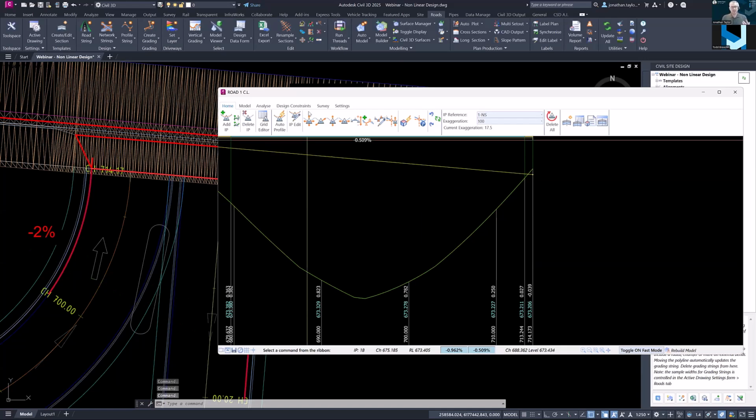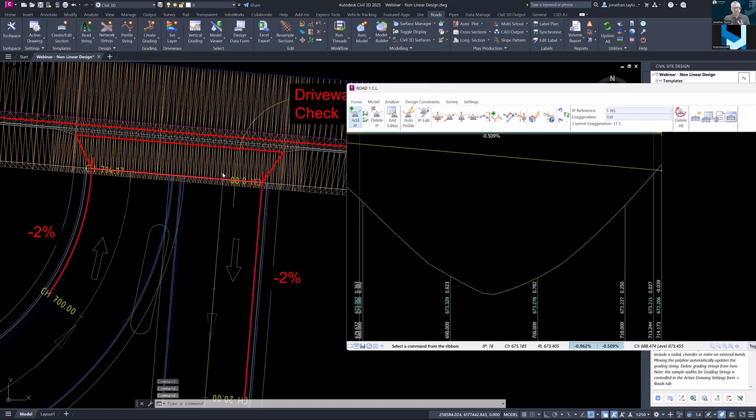So my center line, and by the way, if you were designing this with two separate strings, which I've seen obviously a lot of people would do, you've got a car park string or some kind of driveway string on the left side, which is a grading string, totally independent, and one on the right side, which again is totally independent. You've basically done the edge of your driveway, just using that technique. Okay, so this is the thing about this webinar, is trying to show you some techniques to adopt that could be applied in other ways. And certainly that little surface extend, when I've shown people that and they realize, oh, okay, so that gives me a little bit of surface to play with, I don't have to make sure I'm exactly on the boundary, is a great tool to apply.